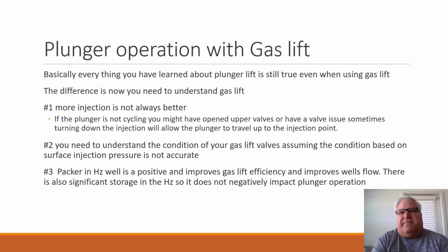Now, the reason the packer works is, I was talking about how that fluid slams past the end of the tubing, and you constantly have that liquid level sitting up above the end of tubing. Well, when you get rid of that ability, the fluid that's coming towards the end of tubing hits the end of tubing. There's a packer there. It actually forces all of the liquid into the tubing before the energy that drove it there can push past it and be dissipated.